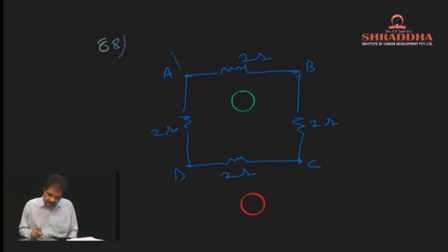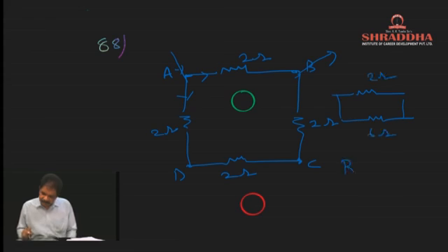So between this, if we consider, current is dividing here, in these 3 the same current is flowing, so all these are in series. So the effective circuit will be like this. Here 2 ohm, this will be 6 ohm. R_AB, they given it as R1. So this value will be 2 into 6 by 2 plus 6, 8. The 2 fours will cancel. 6 by 4 means 1.5 ohms.